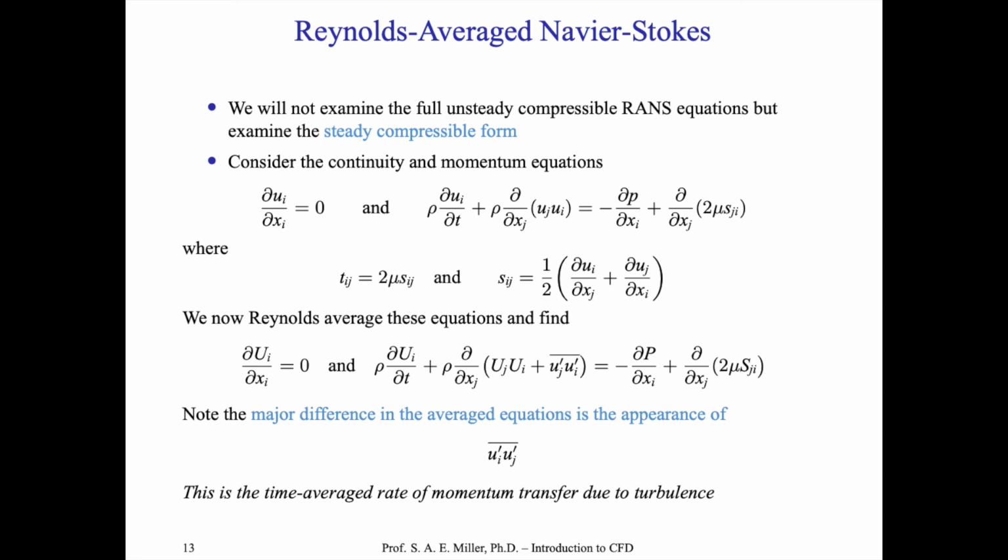So now the power of these equations is that we're able to find the averaged values of velocities and pressures, etc., which is something we can measure in wind tunnels and use for prediction. The difficulty, of course, is that from this nonlinear term we have an extra term here. This is essentially called the Reynolds stress term, and it is the major difference in the averaged equations. It is u_i prime u_j prime bar, the average of the two velocity fluctuations in the convection term. You can do something similar to other equations, like the energy equation, if you're working in the incompressible framework.